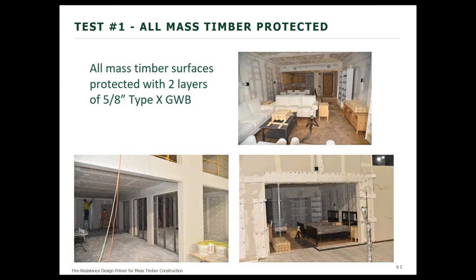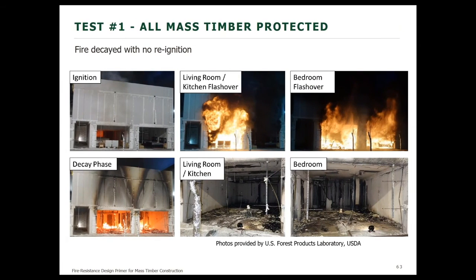These are some pictures showing how they are loading up for the test. All the surfaces, you'll notice, are protected with 2 layers of 5/8 inch Type X gypsum wallboard. Again, this is test number 1.